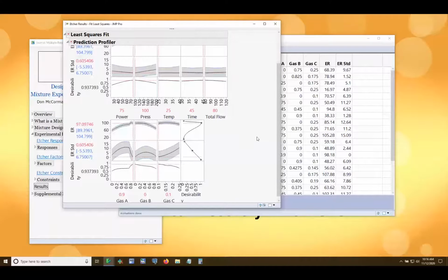And there you go. Now you see that it's putting more emphasis on that etch rate, and I'm coming closer to that target. So that's the flexibility I have in terms of using that optimizer. It's relatively straightforward, fairly simple because I only had two responses to optimize. Often you're going to find that you need to compromise because you can't completely hit absolutely perfect values for all of your responses, but you can use that importance to balance where you are.